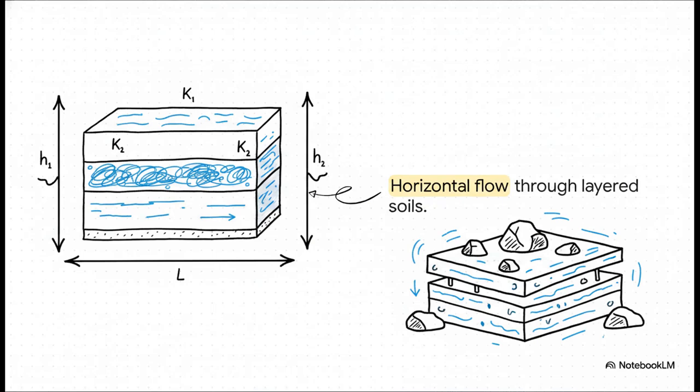And measuring this hydraulic head is absolutely crucial, because underground environments are rarely uniform. The Earth is layered with all these different conductivities: K1, K2, K3, and entirely different thicknesses. The hydraulic gradient, which relies heavily on our hydraulic head calculations, applies uniquely to the flow through each of these individual horizontal layers. Without knowing the head, we really couldn't understand how water navigates this incredibly complex underground obstacle course.